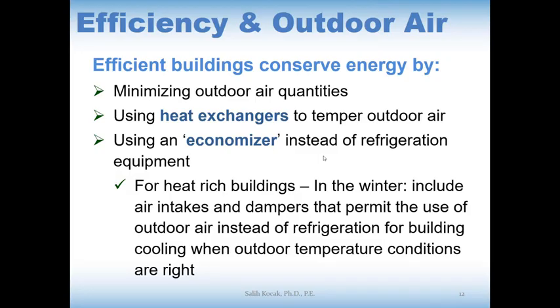Efficient buildings include heat exchangers to transfer heat between exhaust air and incoming outdoor air. This is the most important thing. Exhaust air means the air that is taken out of the building. The heat exchanger takes that heat and gives it to the incoming outdoor air.